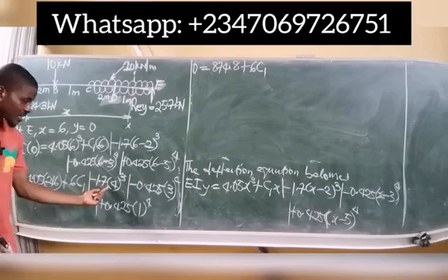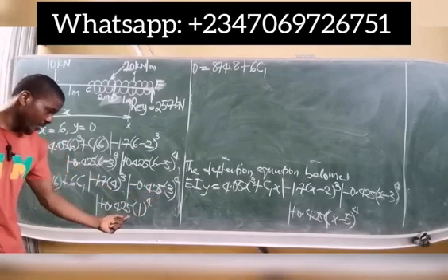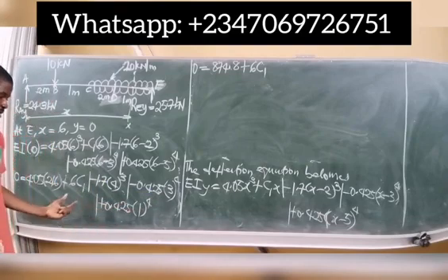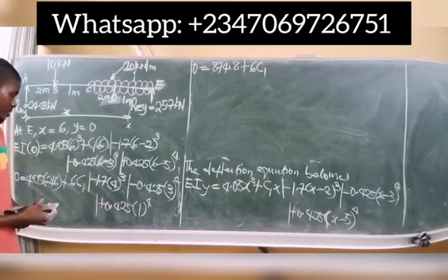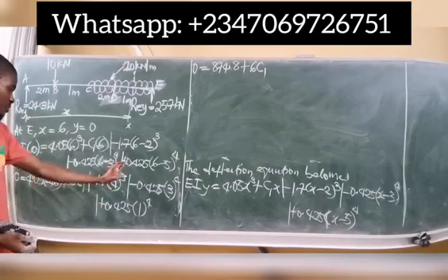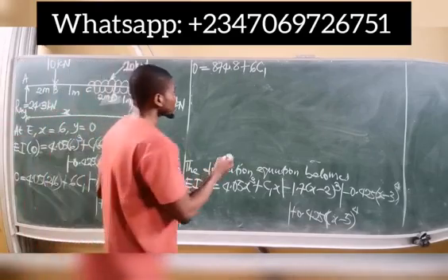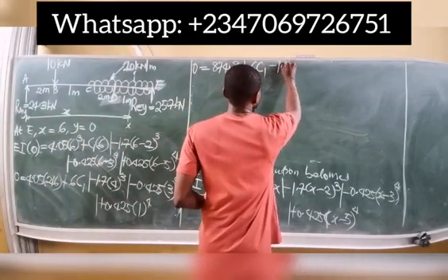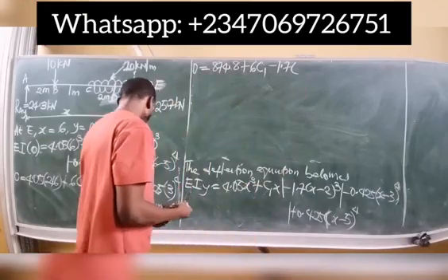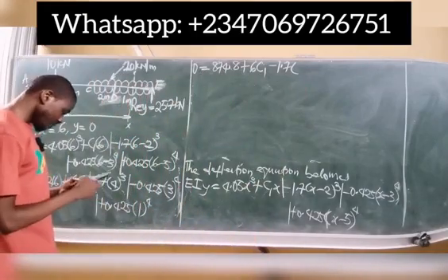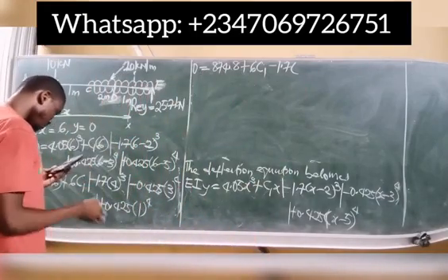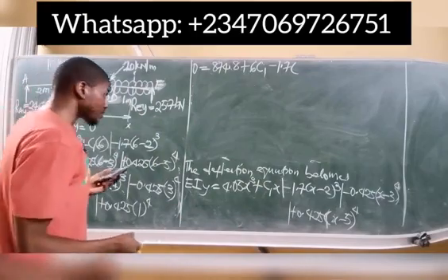The values in the bracket are now positive. We have 4 here, you have plus 3 here, you have plus 1 here, not less than 1. So we can now solve with these values. Simply remove the Macaulay bracket now and solve. We simply have minus 1.7 into 4 to the power of 3. That's 64.